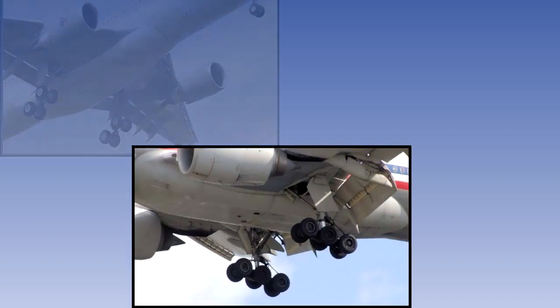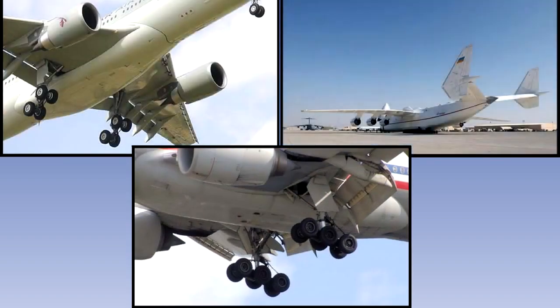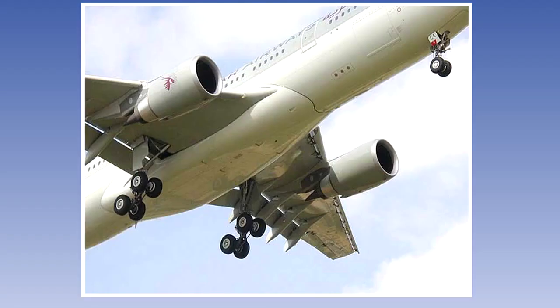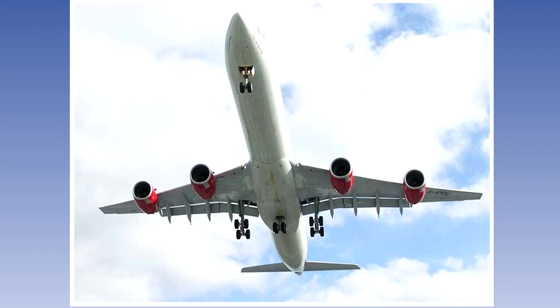The geometrical arrangement and physical location of landing gear units on aircraft is by no means standard. The type, size, and position are decided at the design stage, having already taken into account the many factors that must be considered. The main considerations are the size and weight of the aircraft, the role the aircraft will fulfill, whether it has a high or low wing, and any associated gear stowage problems. Most modern aircraft will have the main landing gear attached to the wing, with some of the larger types having both wing and body gear.